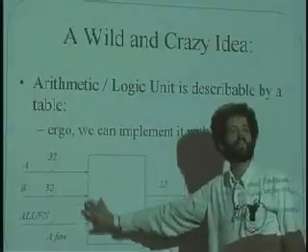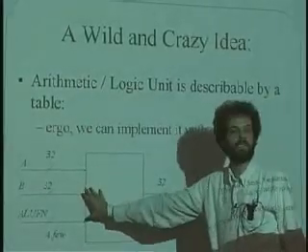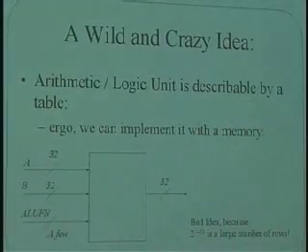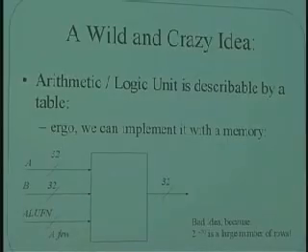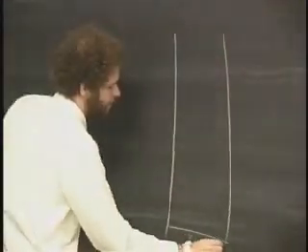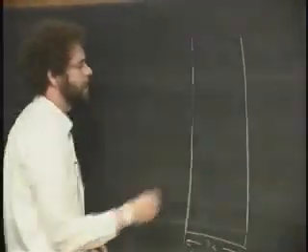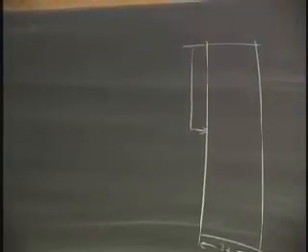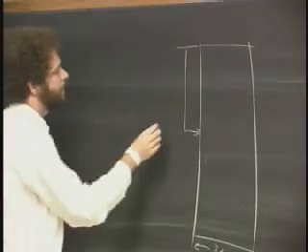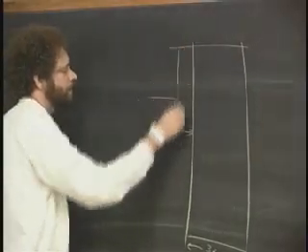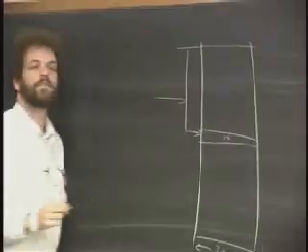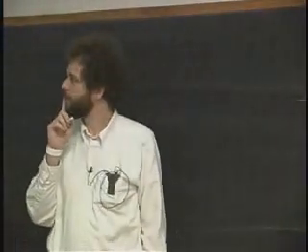This is simply a table that has 69 bits in and 32 bits out. And that means that I can describe exactly what that function is by having a table like this, and the output is going to be 32 bits wide. So every entry in here is going to be 32 bits wide. And as input, I'll have all of those bits that go in there, the 69 bits going in there, and that will control how far into the table I look, and out will pop the answer that I'm trying to get. Now, what's wrong with this thing?